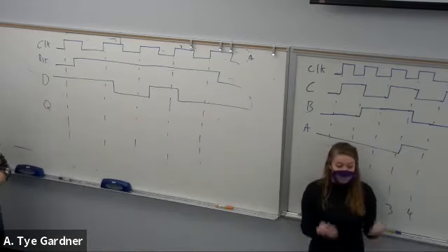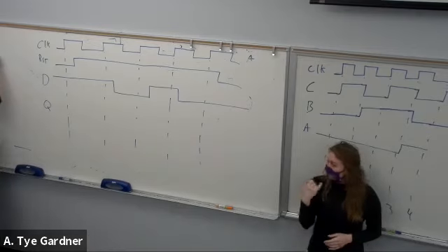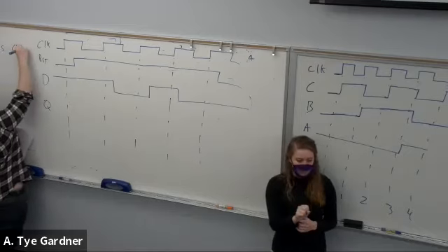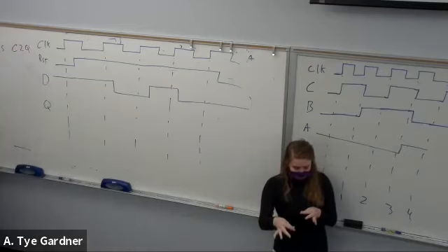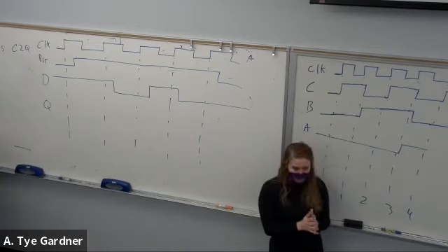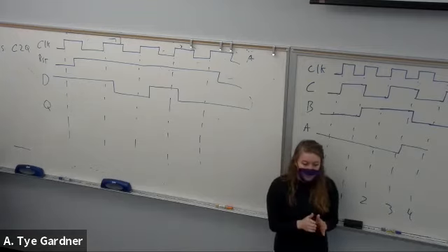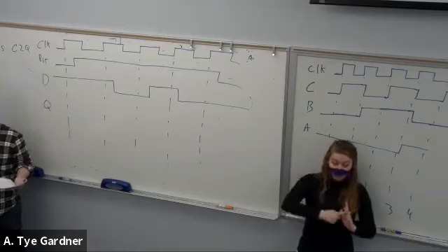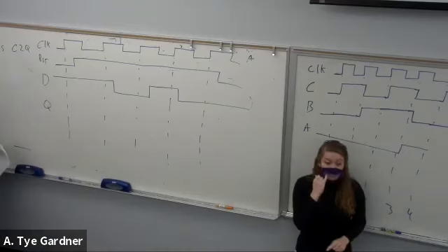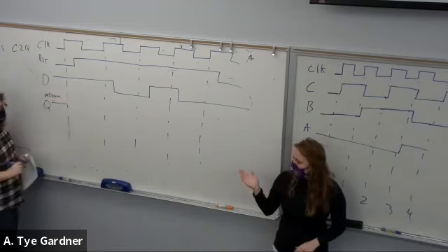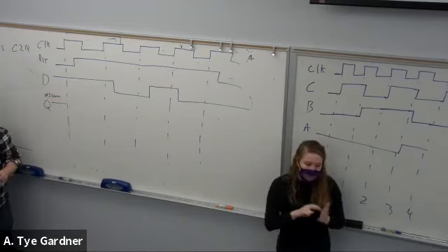Now, the question would be, given that there is a 4 nanosecond clock to Q delay, draw me Q. Right? Now, there's a couple of things that you want to be aware of. First off, I will usually try and tell you that Q starts at something. If I don't, you could do something like assume 1, right? And just let me know you're making an assumption.